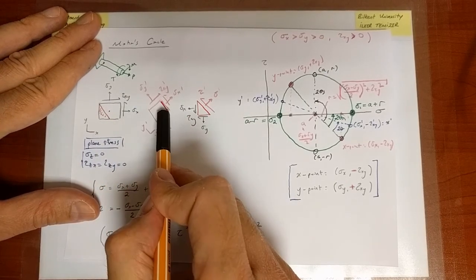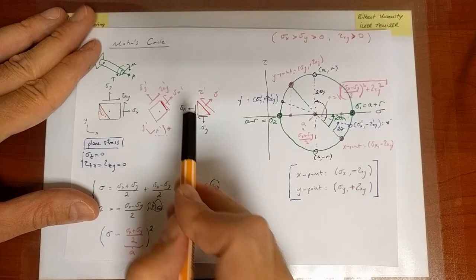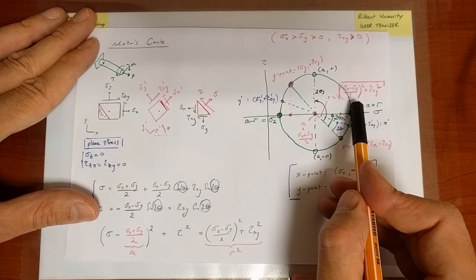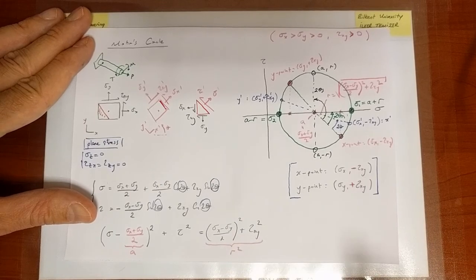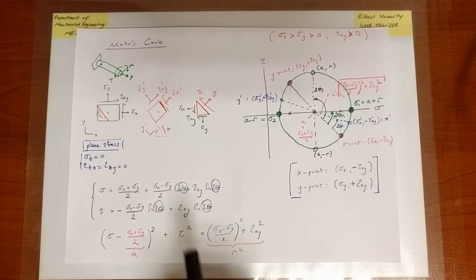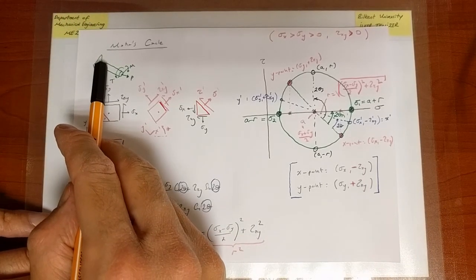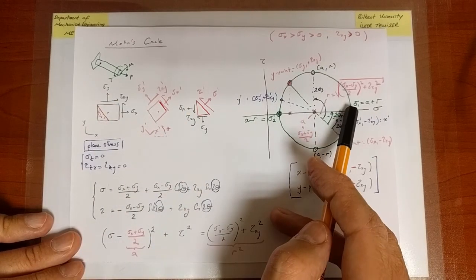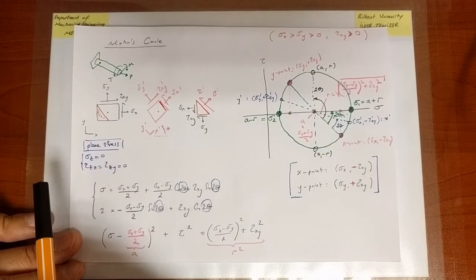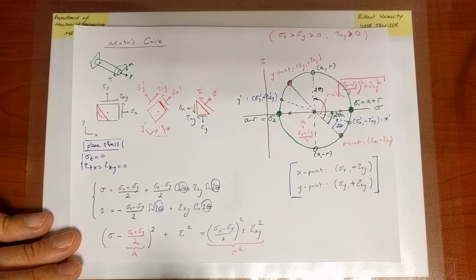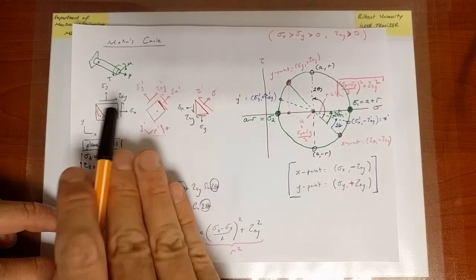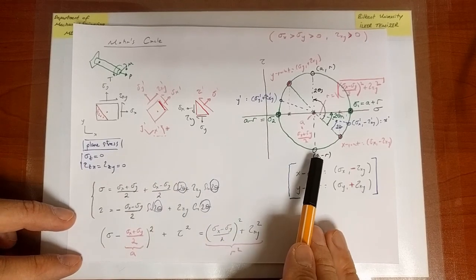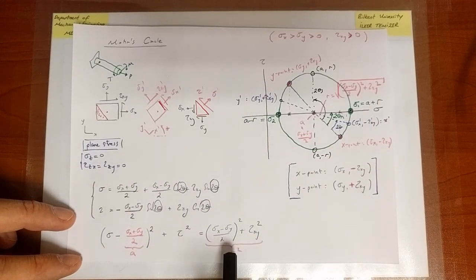We're just picking planes with different orientations so that I can ultimately find where the normal stress is at maximum, where the shear stress is at maximum. And why do I want to do that? Because I am searching at a point in the structure what those critical values are, normal or shear stresses, because the material fails according to a function of those stresses. And the Mohr circle is helping me identify those values in a compact fashion without having to memorize anything.